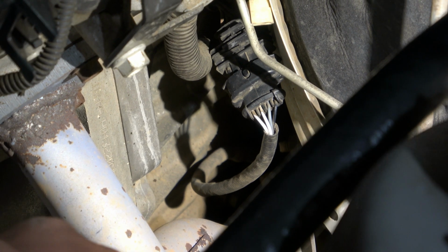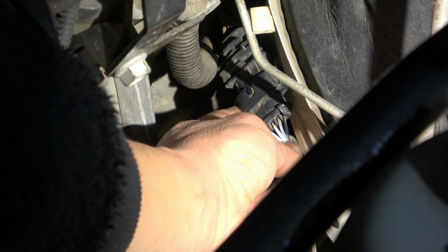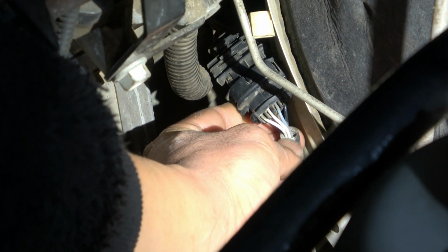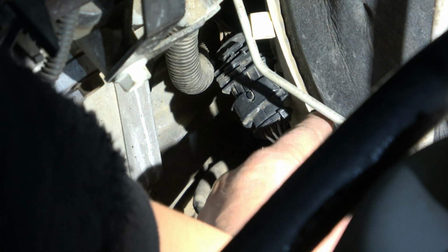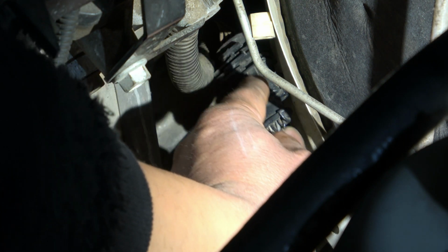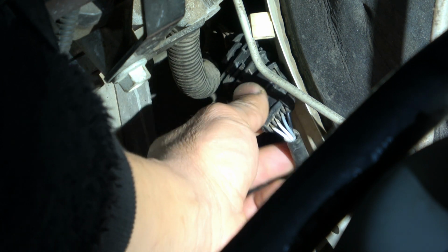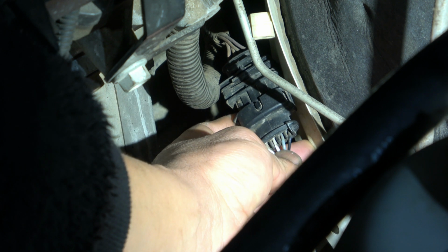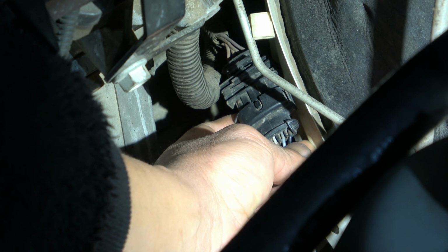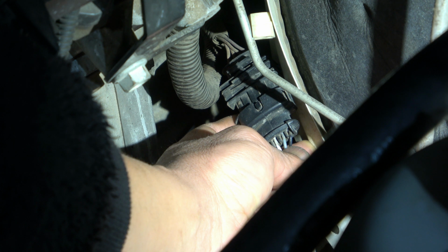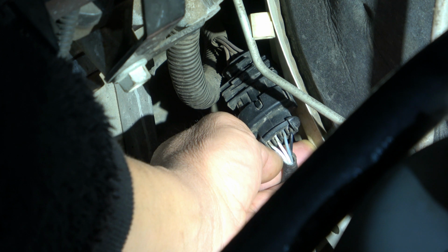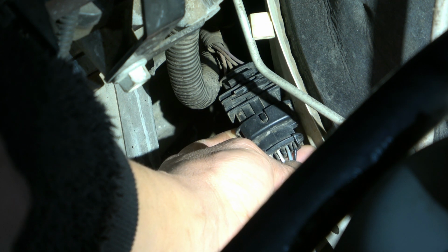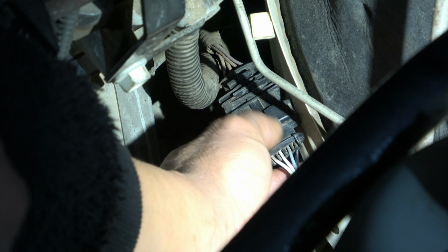In this wiring here, you can see there's 2 white color wires. This is going towards the sensor, down this way, and up this way goes to the engine computer. So 2 white color, and one's gray and one's black. The 2 white color is for our heater circuit. Black and gray color is going to be signal and earth.